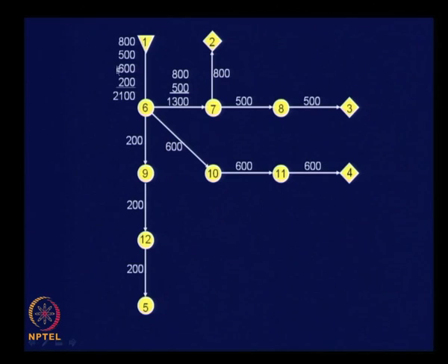Now sum up the assigned units of traffic volume for each of the links. We have 4 components for 16 totaling to 2100 PCU per hour, and there are 2 components for 67 amounting to 1300. All other links have only one component. Now the picture with regard to link volumes is very clear to us.